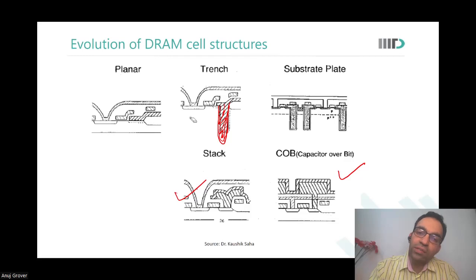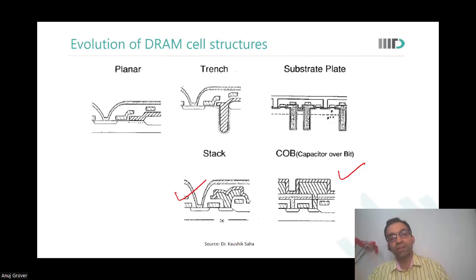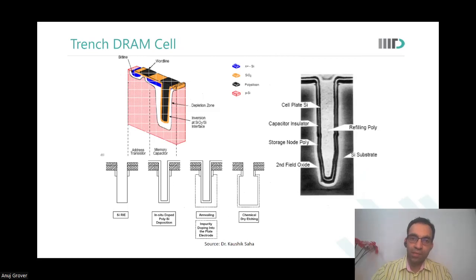So now in the trench capacitor, you do not even need to go up high and do not need to waste area due to contacts and vias or anything like that. The trench can be designed right there inside your memory cell, right next to the source drain region. It can be connected just like this. You see the trench is connected to the transistor source drain region.